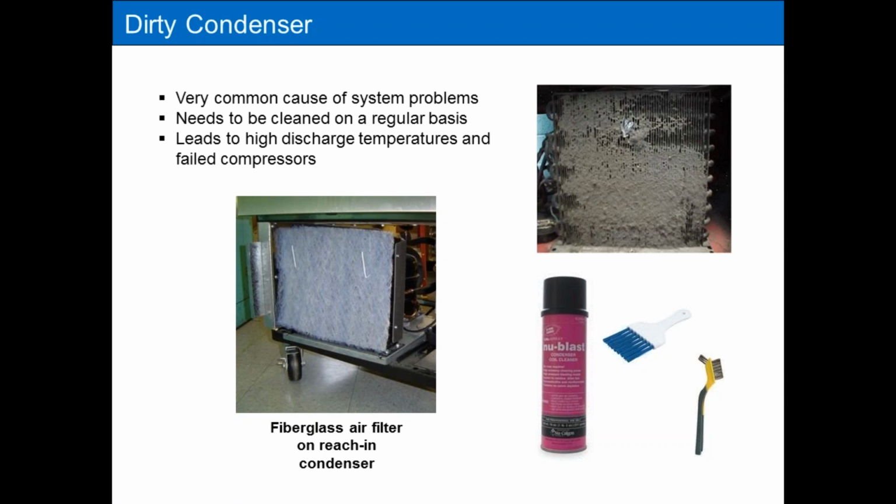Easy cleanup: pull it out, put a new one on, so that's very nice. It does make you have to go back on a regular basis to clean them because these do get plugged up more frequently than just the coils. So you've got to tell your customers, if you're going to go to this approach, that somebody needs to change these on a regular basis, because they will plug up faster and lead to a loss of airflow more quickly than if you didn't have it on. But if you do keep up on the maintenance, it's a quick cleanup, right? Change it out, put it on. So I like it from that point of view.